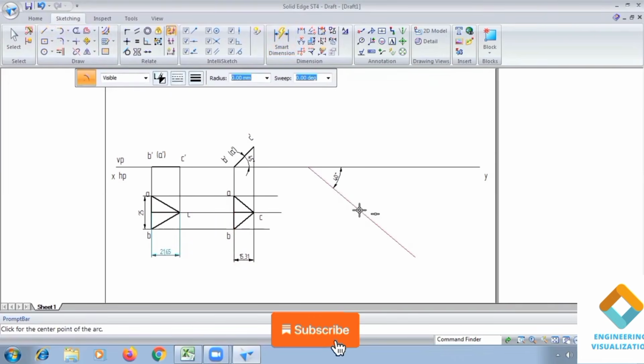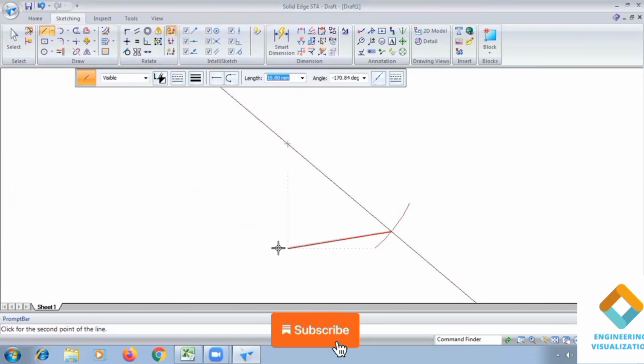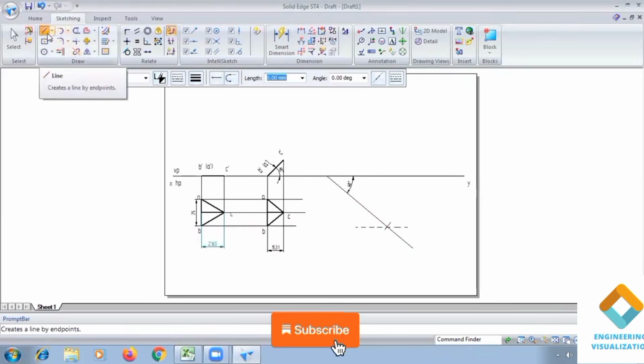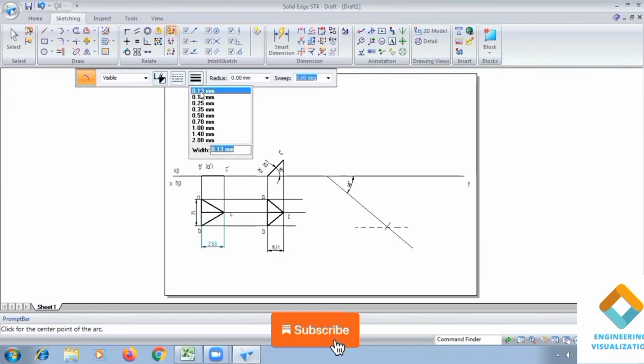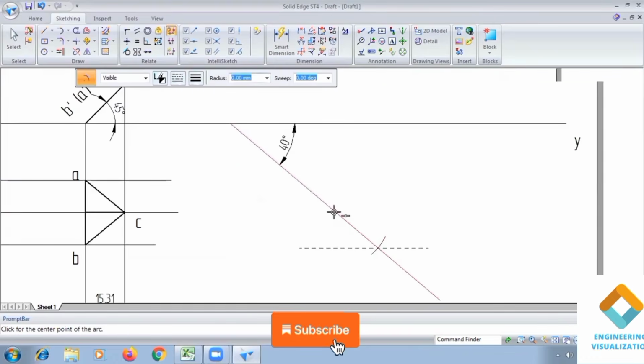So go to arc by center and cut the first arc of 21.65. Cut the arc. Now draw the locus line. Let's draw the locus line here. Then go to arc by center here. So take second arc length 15.31. Okay, from this reference point, type radius 15.31, enter and cut the arc.